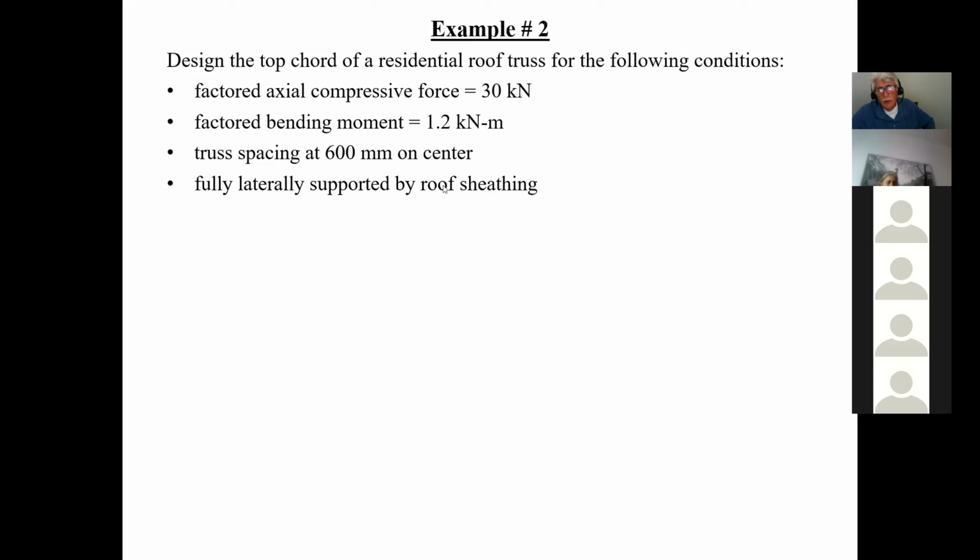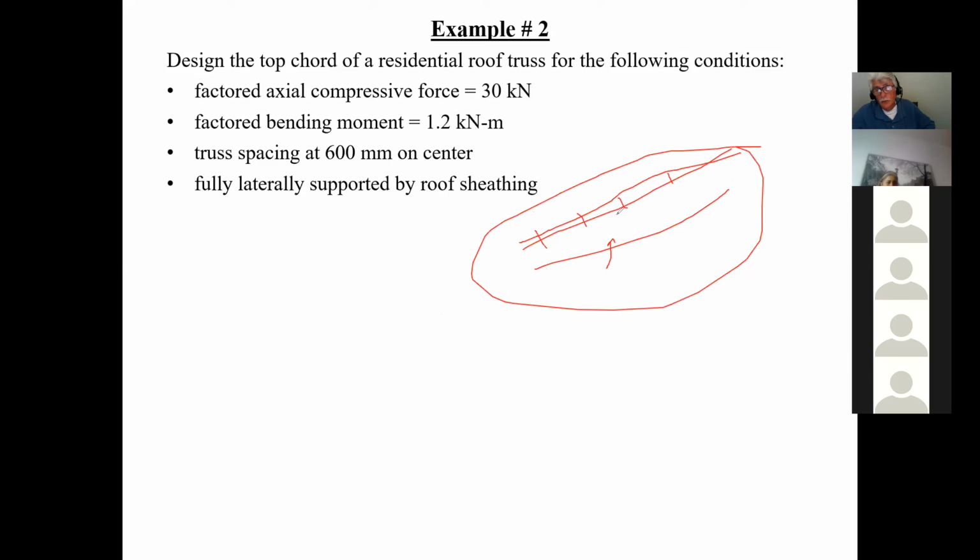Fully laterally supported by the roof sheeting. Oh, that's good to know. Okay, so does everybody understand what this means? In other words, here's a top chord like this, and I have some roof sheeting here, and it's nailed and it's laterally supporting the top chord completely, okay? So this is good to know, that the roofing is going to laterally support the compression member.